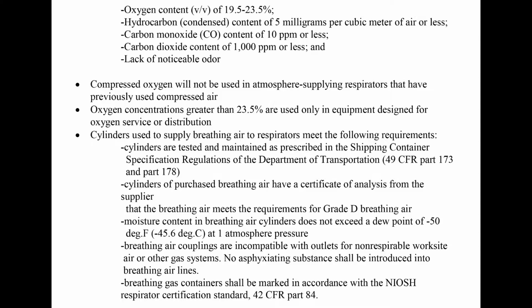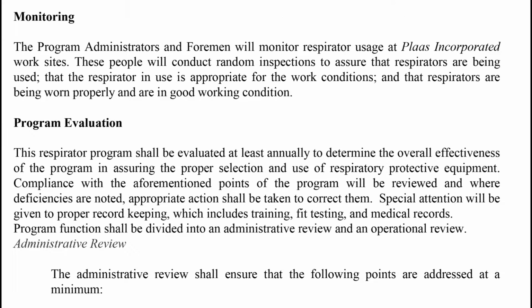Breathing air couplings are incompatible with outlets for non-respirable worksite air or other gas systems. No asphyxiating substance shall be introduced into the breathing air lines. Breathing gas containers shall be marked in accordance with NIOSH Respiratory Certification Standard, 42 CFR Part 84. Monitoring. The program administrators and foremen will monitor respirator use at Plaas Incorporated work sites.